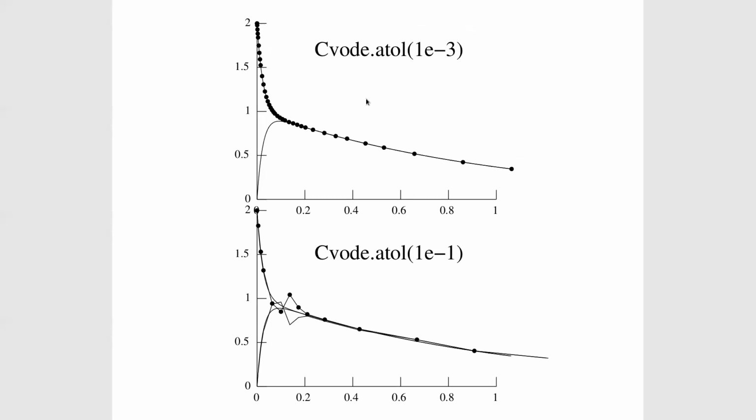Adaptive integration, I'm going to mention this here, uses a set of algorithms that calculate how big a time step to use based on the local error at each advance. When it starts a solution, it takes a very small time step. It makes an estimate of local error.